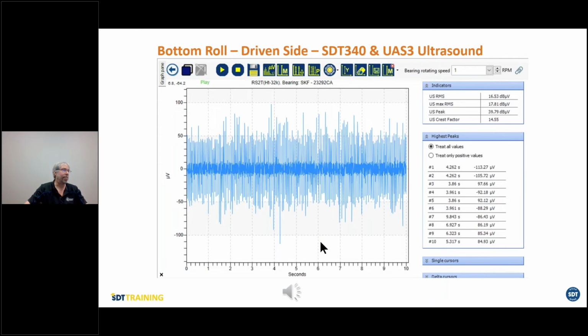Vibration is not designed to do that. Ultrasound is. The whole point of using ultrasound is to bring the high frequency stuff to a low frequency area so that your ears can hear it. When you have some kind of headphones for vibration, you hear the whole machine. But this is specific for a certain frequency. It's a filter.